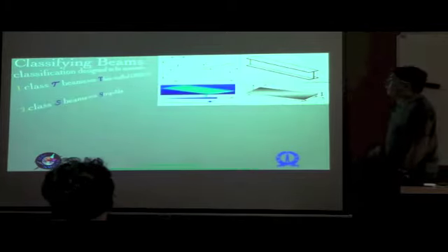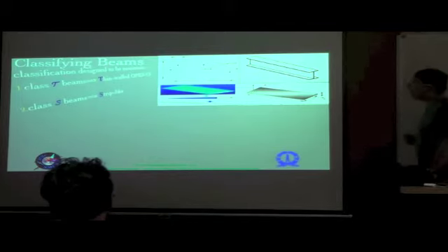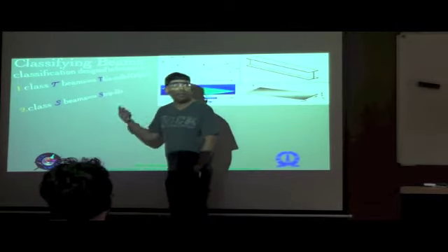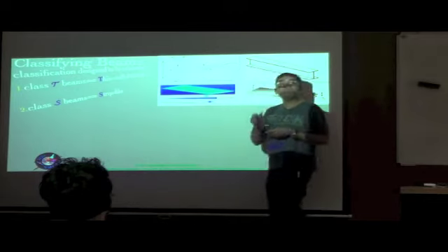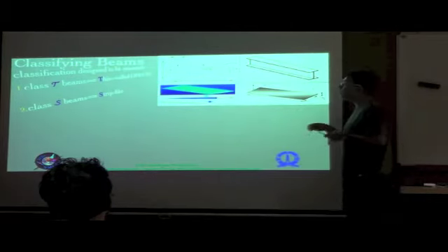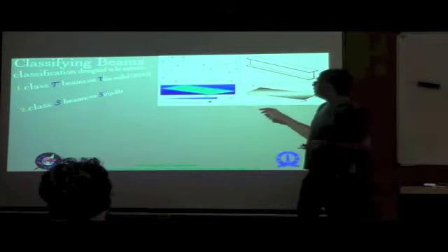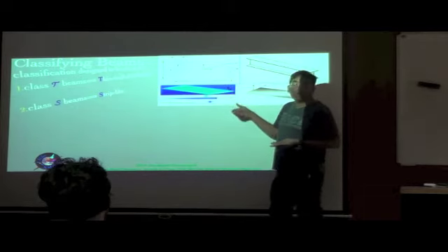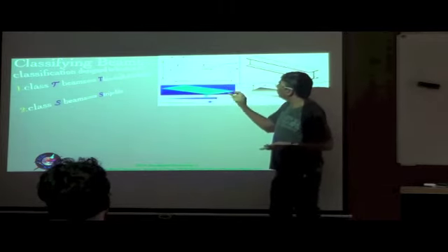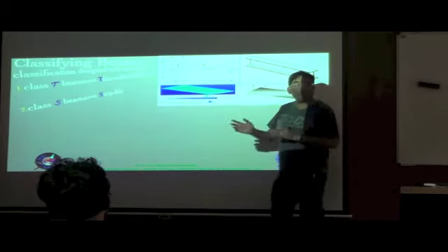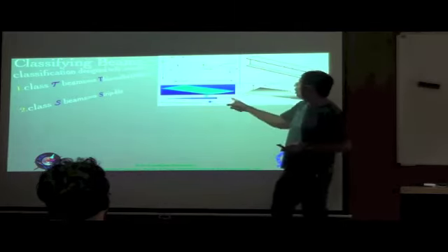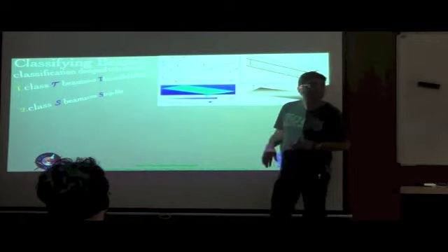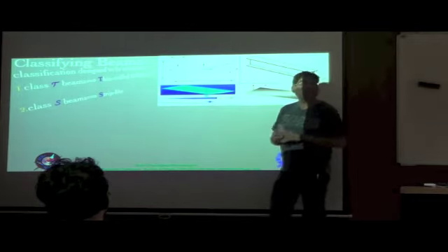The next class is the class S beam, where the letter S stands for the word strip. So they are strip-like beams, which is not restricted to thin rectangular cross sections alone, but also any other thin cross sections, such that if you take two directions which are orthogonal, you see that the dimensions of the structure are very different from each other in terms of an order of magnitude. So if you have a thin airfoil cross section like this, even that can be classified as a strip-like cross section, or in other words, what we call class S beams.